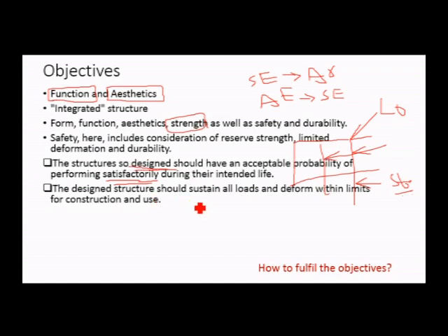Means all the loads during construction and use as seen in various conditions. The structure having insufficient strength of concrete fails in bending compression with the increase of load, though the deformation of the structure is not alarming on the other hand.